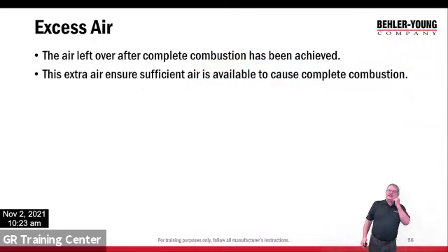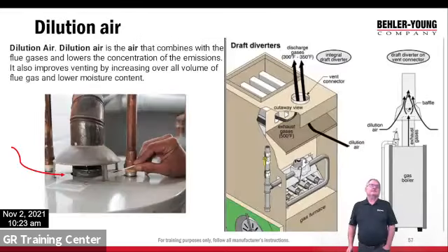Okay, excess air is leftover air. After combustion, the measure of excess air is one of the measures of complete combustion, because if I've got a lot of leftover air, that means I had enough. That's part of the key. So the extra air ensures sufficient air is available to cause complete combustion, and we can measure that excess air.